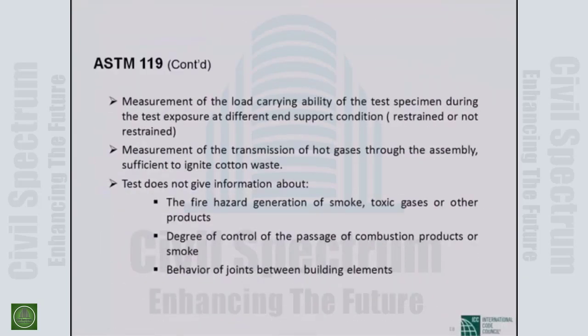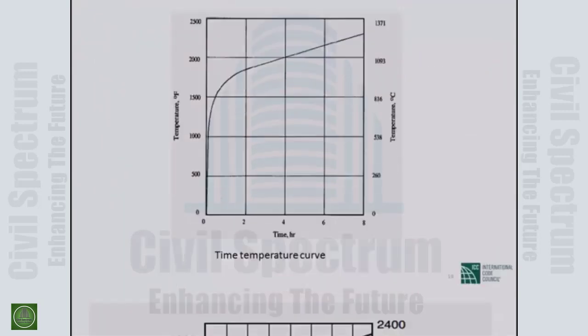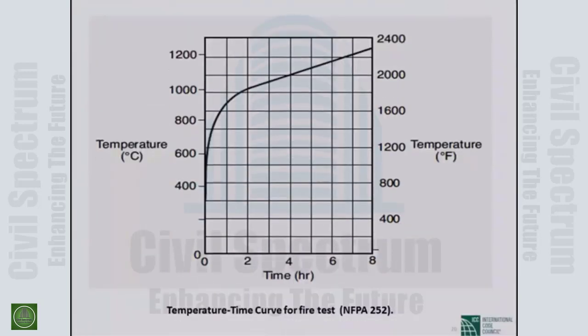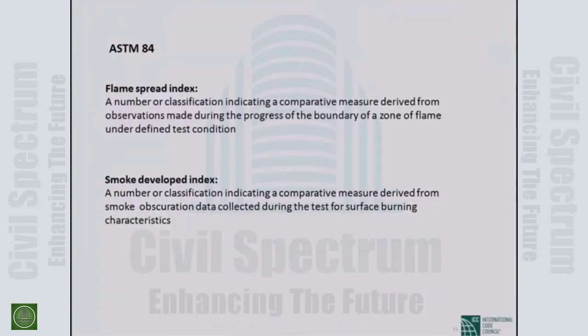So when we test 3 hour, 4 hour, 1 hour, that means it will withstand an endurance strength, and it will withstand a hose stream pressure, and similarly it will withstand a definite type of temperature. So I think you have understood that the testing of a rating of the material or the element or the structure is not only the temperature, not only the hour, it is load, pressure, and other things. So when it is actually tested, all these parameters are tested and reported.